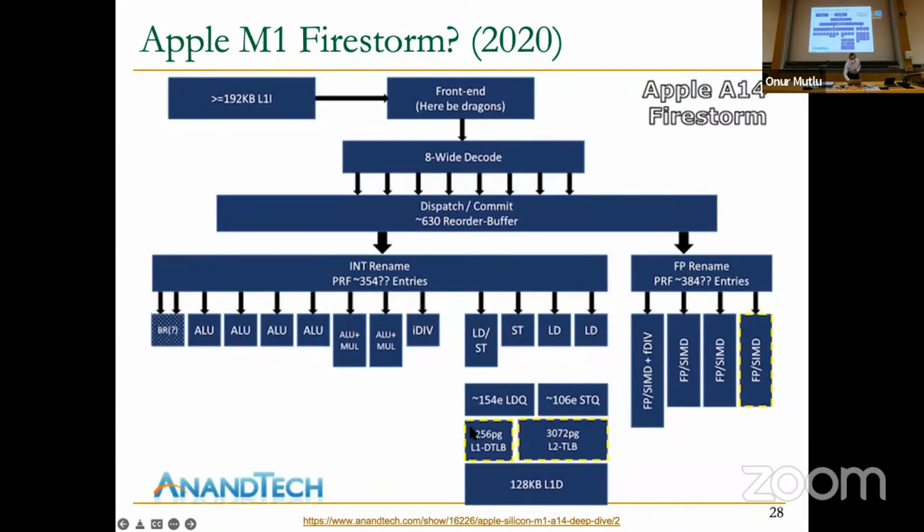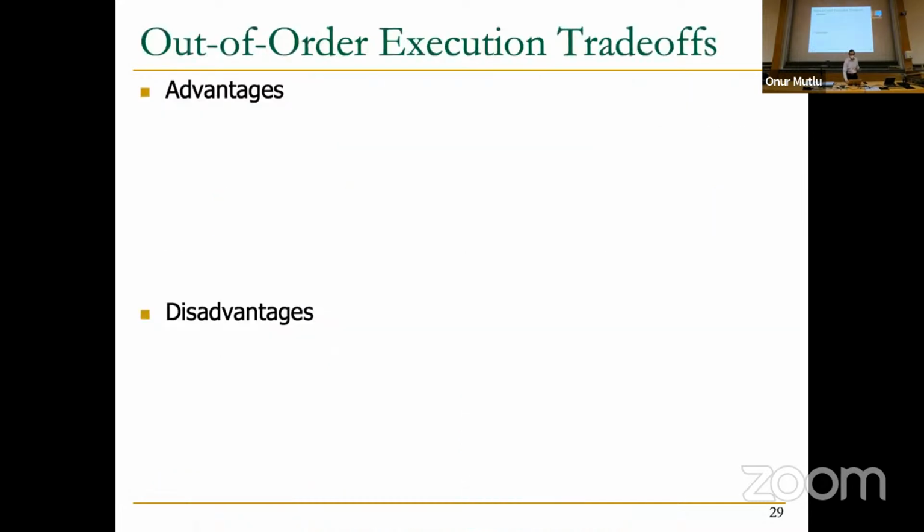And this part we're not going to talk about. Even this is the hairy part of the machine, actually. This is the worst part of an out-of-order machine. How do you handle the loads and stores? I'm going to point you, as I said yesterday, to a short lecture from last semester's. It's a 24-minute lecture. So if you're really interested in how to handle loads and stores and out-of-order execution, you should watch that lecture. We don't have time this semester, unfortunately, to talk about that. But as you can see, that's a hairy part. These structures tend to be much smaller than the other structures. It's not easy to scale up those structures, and you will learn why that is if you watch that lecture.